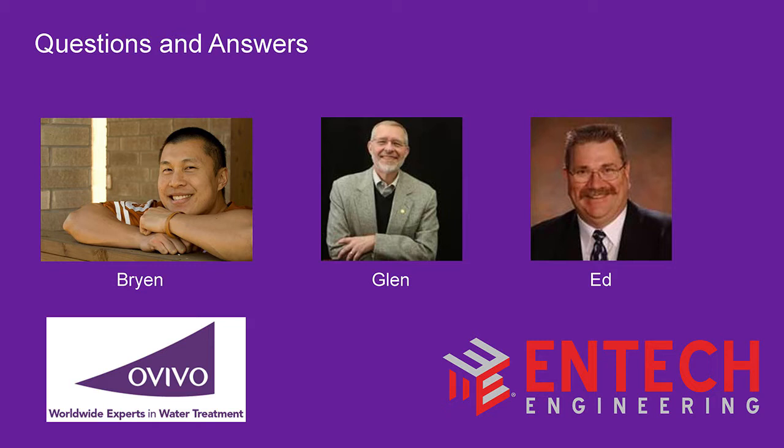Thanks, guys. And last question, and this is for Ed. For the Frackville plant, what were they using for aeration before you installed the shear tubes? I hate to say anything by brand name. We were using the stainless steel tube diffusers. They're 18 to 24 inches long. They have the large holes on them. That's what was in there.